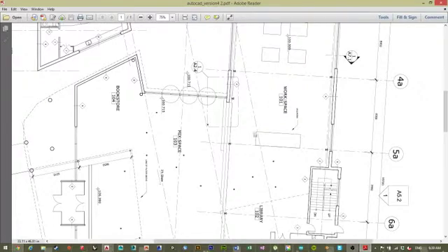So I didn't draw these from scratch. I had my 3D model, but obviously the lines are more just the outline, and then from there I tweaked. I brought those curves into AutoCAD and then made a nice set of plans. So you can bring the section cut from Rhino into AutoCAD and then assign the lines. Yeah, so they all come in the same color. They all came in on layer 0, but then from there I put them all in the right layers. I obviously fix thicknesses and stuff because my 3D model is usually not perfect.